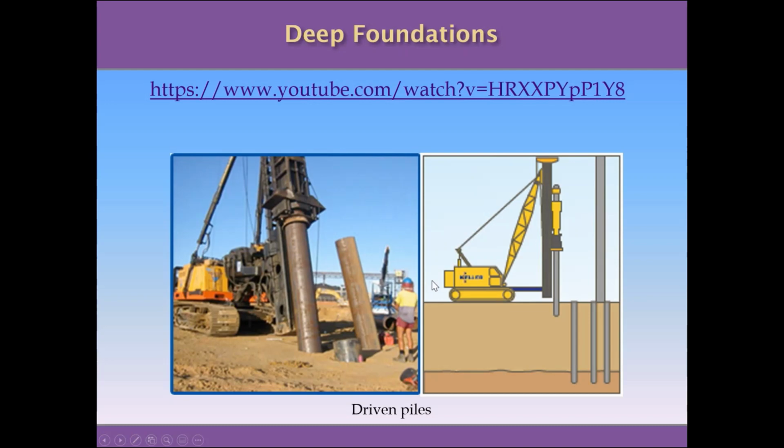This is the funnier one. If you watch this video, you will have fun seeing how these driven piles are installed, because they are basically hammering on the soil, and it's a very effective system to found tall buildings. It produces not only the spread of the forces by two mechanisms, the friction and the bearing capacity at the tip of the pile, but also a consolidation of the soil, improving considerably the strength of the soil in the area of the foundation of any building.